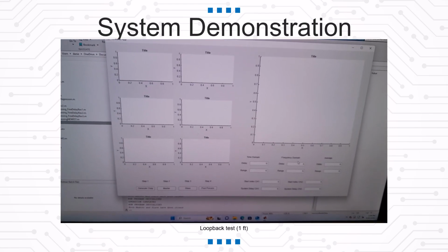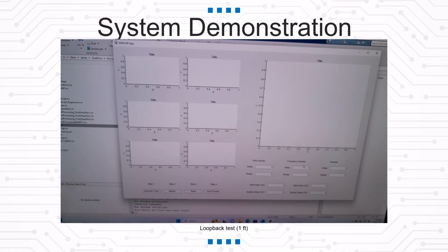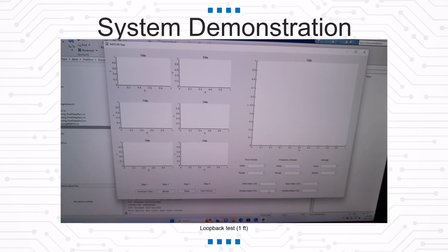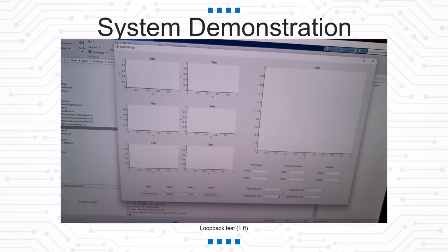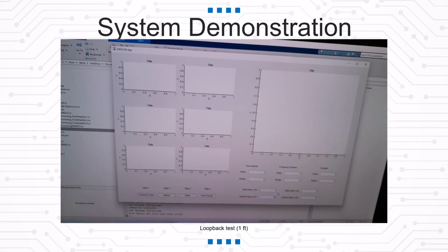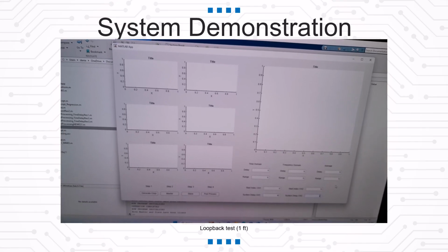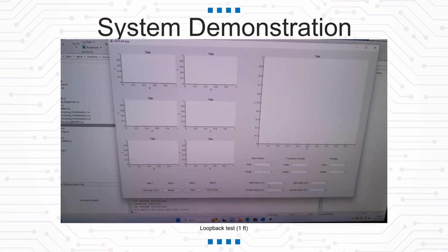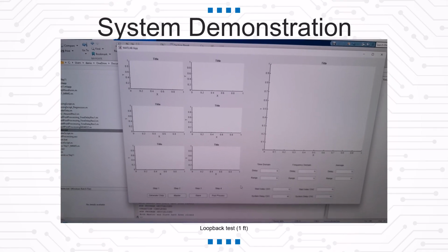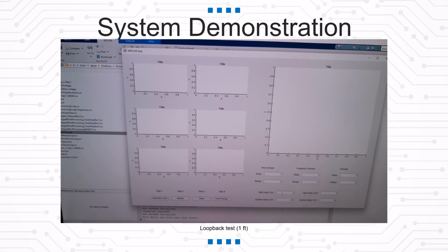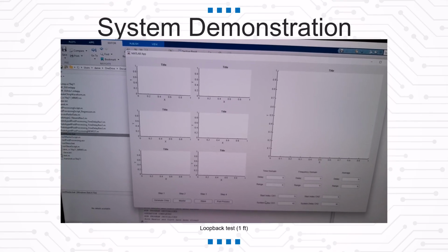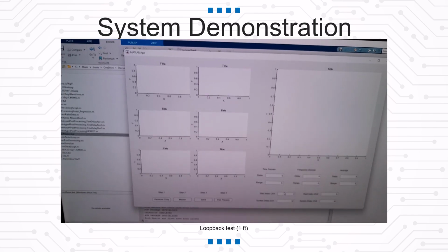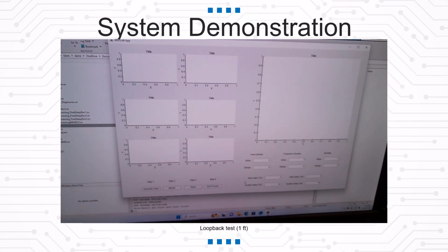With such a small propagation delay, this is kind of pushing the system to the limits, and we're just comparing to see how agreeable they are. From previous attempts, I know that the start index typically starts at 42. Since we're doing a 1 foot cable, we're just going to set the start index to start the system delay offset to the start index. So we're just going to measure that last little bit of propagation delay.